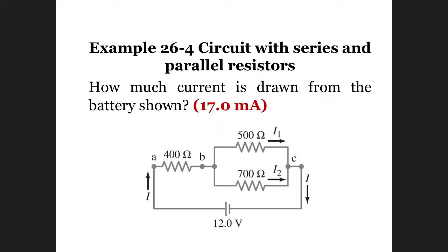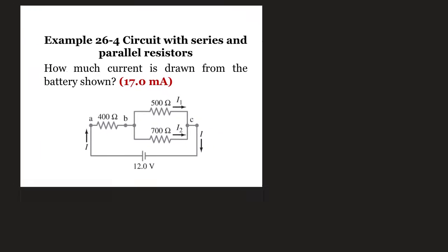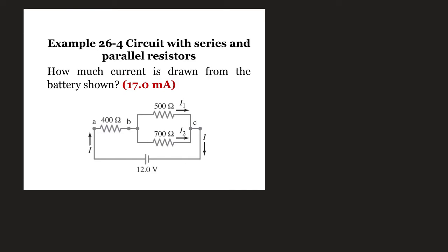So this is the question where you need to find the resistor equivalent first, for you to find the current drawn from the battery. Make sure that you find the resistor equivalent first. Therefore, please solve the resistors that are in parallel first. Then combine them into one, and then you move to the next step, whether it's going to be series or parallel with the next one.